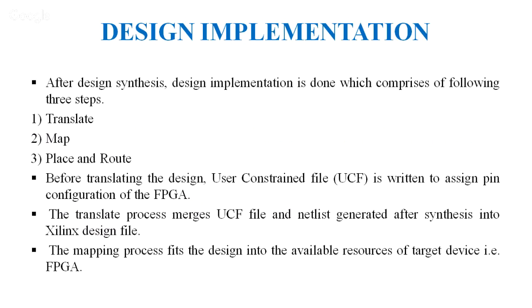Next is implementation. Before implementation, we need to make a UCF file. Now, what is this UCF file? Basically, a UCF file is a user constraint file. Because FPGA is programmed with a hardware description language, if in our program we take some inputs and outputs, we have to define on which pin we give input and on which pin we take output.